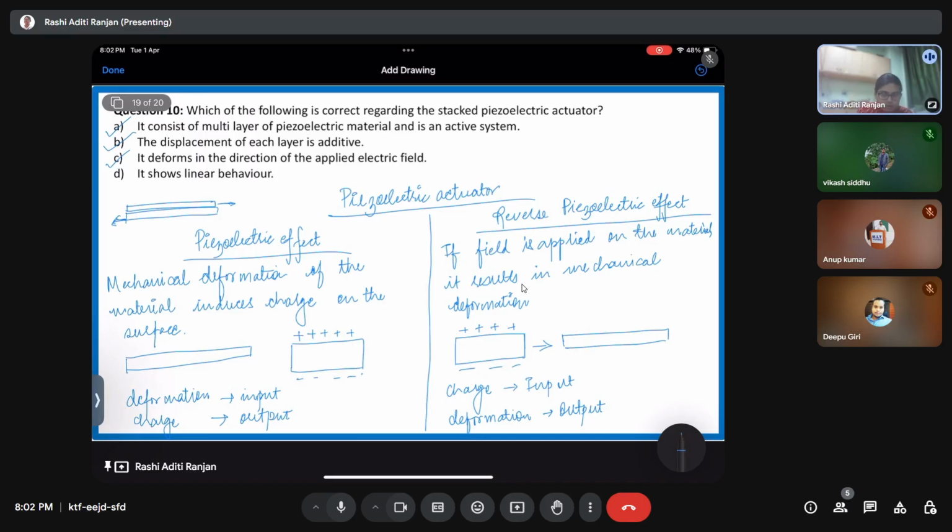But if I talk about a piezoelectric actuator, if it's a crystal, we cannot talk about the stiffness. If it's an elastomer, now in the market there are piezoelectric elastomers as well, wherein we take very small crystals of piezoelectric material, and then we mix them into the elastomer. Like we usually take the elastomer, we heat it up to a certain temperature, then it converts into the fluid form, then we mix the piezoelectric particles, and then it behaves like a piezoelectric actuator.